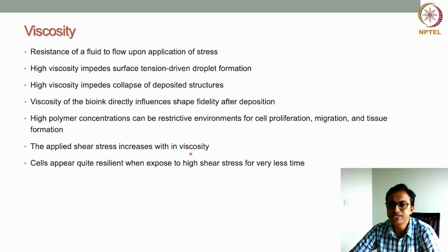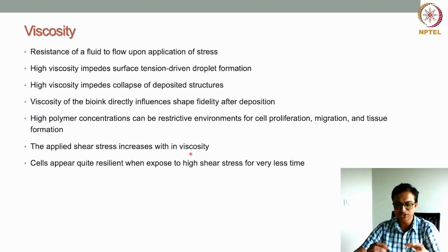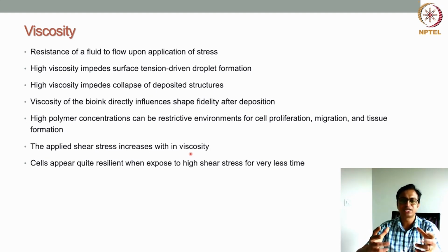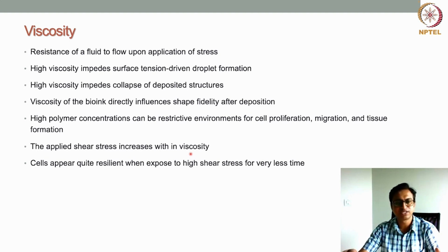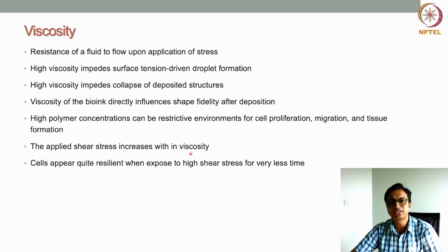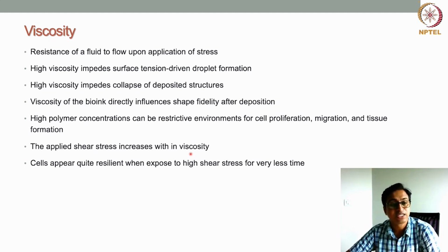It prevents the collapsing of that structure, because the viscosity will hold the material together. So the viscosity impedes both surface tension driven droplet formation and also collapsing of the deposited structures. Another important thing about the viscosity is that it directly influences the shape fidelity after deposition.